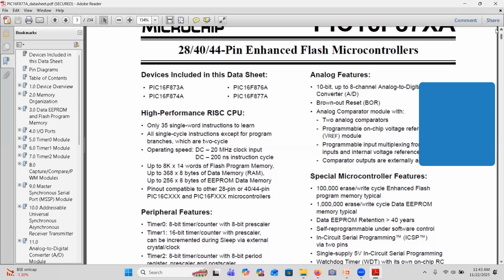If all 4 bits are 0, they will choose the first channel and digitize input from the first channel. In that time, though you have input in other channels, those are ignored. They won't take it up.